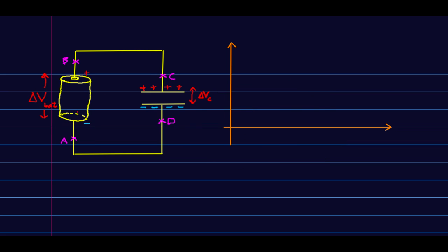Now we're going to look at one of the simplest circuits you can put together. Here's a battery. We'll later on draw these with a symbol, but for now I'm just going to draw pictures of batteries. And it's in a circuit where we've connected the positive terminal to one side of a capacitor and the negative terminal to the other side. And it's all been connected for a while. So remember, we talked about this in an earlier lecture. Electrons would be pulled off of this plate and pushed onto this plate, and eventually there's a big charge on here and the current stops flowing. So there's no current flowing, and we know there's some potential difference, some voltage across this battery.